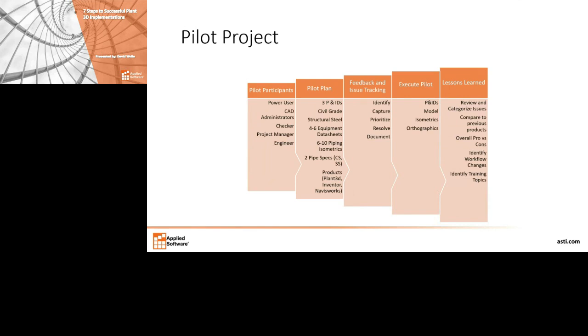An engineer might use a report that's exported from the report creator to fill in more data. And so he might type in specs about the valve or design pressures and temperatures in the line list. And so he would need to know the process for finding the Excel file that he needs to edit, understand that he needs to communicate when he's finished with it or needs to update the change, and if he has access to the software, how to use the data manager to bring in the change and verify that the right properties have been modified.